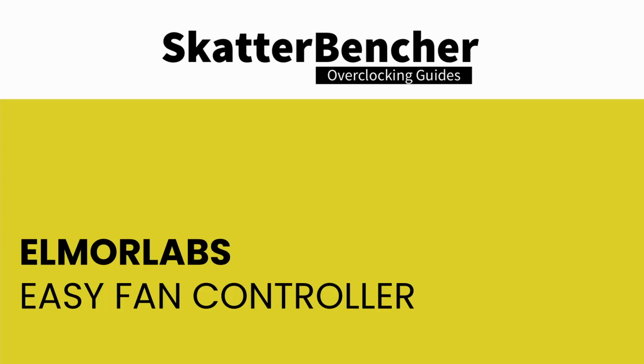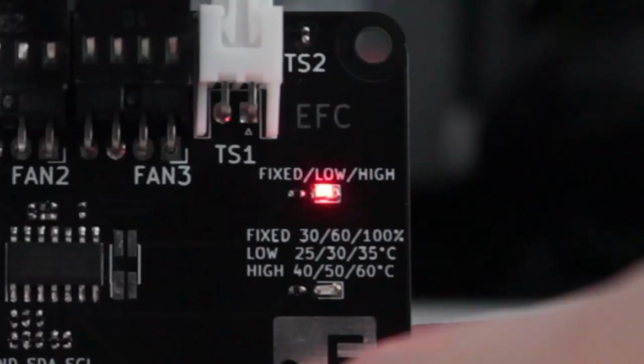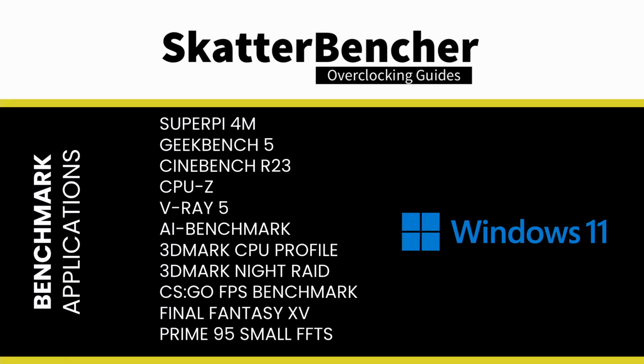I covered the Elmor Labs EFC in a different video on this channel. Without going into too many details, I have attached an external temperature sensor from the water in the loop to the EFC. Then I used the low-high setting to map the fan curve from 25 to 40 degrees water temperature. This is used for all overclocking strategies. We used Windows 11 and the following benchmark applications to measure performance and ensure system stability.